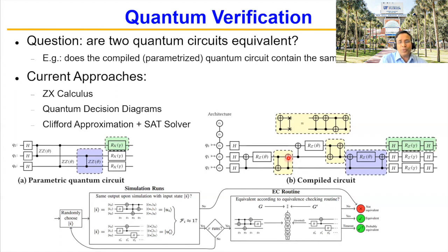Or is it going to produce the intended result? In our case of clustering, are they going to put the same set of nodes in the same cluster or not? If I ask about node 5, would it correctly tell me yes, it's in cluster 1 or cluster 2? In between, if it makes a lot of mistakes, I don't care. So the objective is slightly different, but you are trying to see whether those two circuits are different. That's the equivalence checking problem.